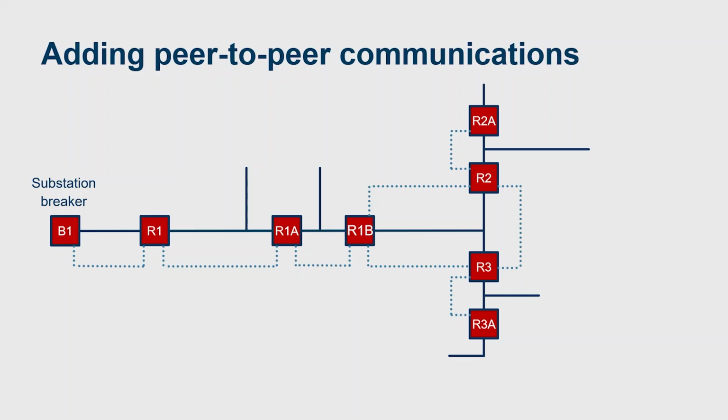We've noticed, though, that a lot of customers who are investing in this number of reclosers are also wanting to perhaps invest in communications in the future. That would add some benefits. If you had peer-to-peer fiber communications for protection speed purposes, you could lower the time to trip down to 3 cycles. And you achieve greater selectivity by only tripping the device closest to the fault.